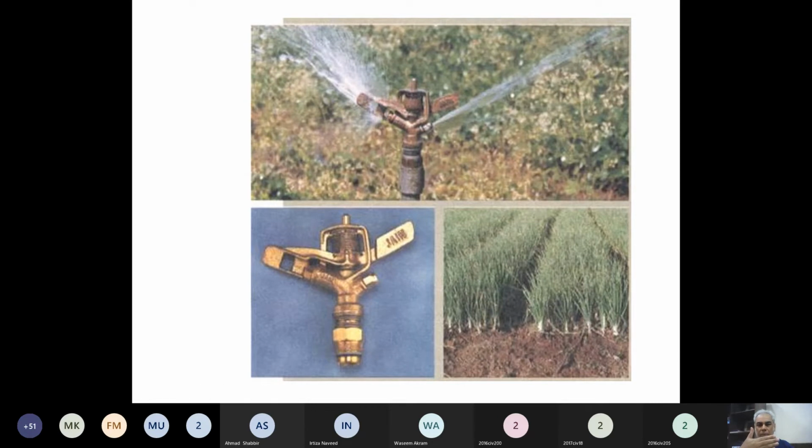angle to the nozzle. So when the jet impinges on this vane, that part of the sprinkler gun goes in the opposite direction, that rotates. This vane is then linked over here with the help of a spring. The spring brings it back. So over here there is a spring attached to it, and the spring brings it back rapidly.